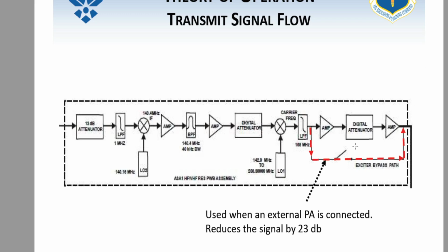That approximate 1,500 miles that we talked about yesterday, which is also in your study guide workbook, is how far HF signals can travel. There have been some instances where I've heard people using HF at nighttime to talk much further, and that has to do with the ionosphere thinning and being able to shoot the signal further. The problem with having too much power, though, is you can actually end up piercing through that F layer and not get your communications across, so that can be a problem as well.